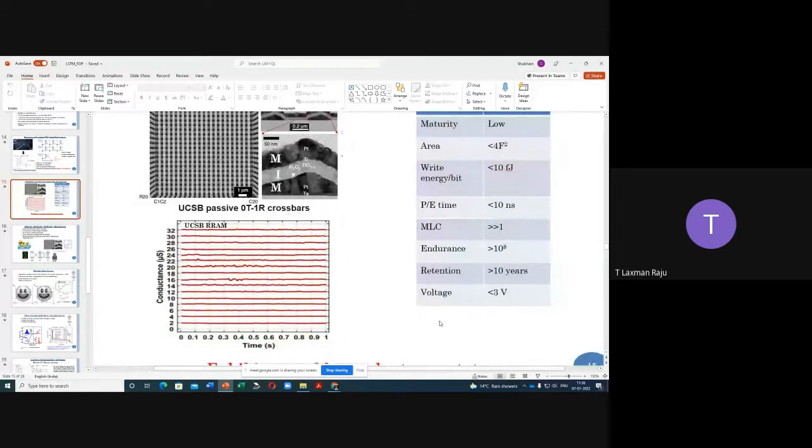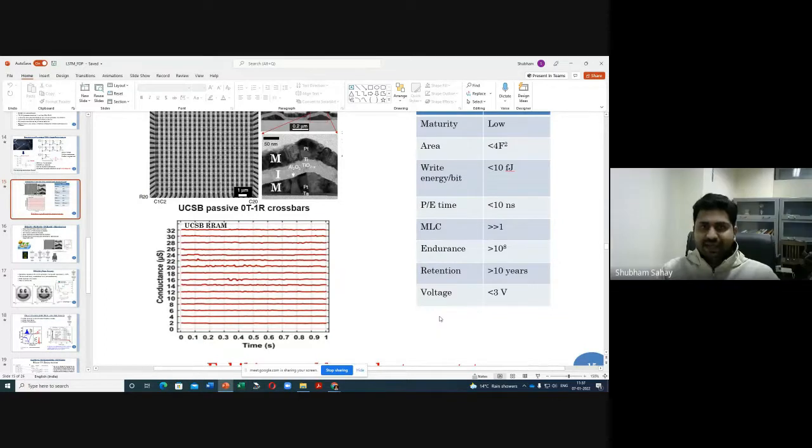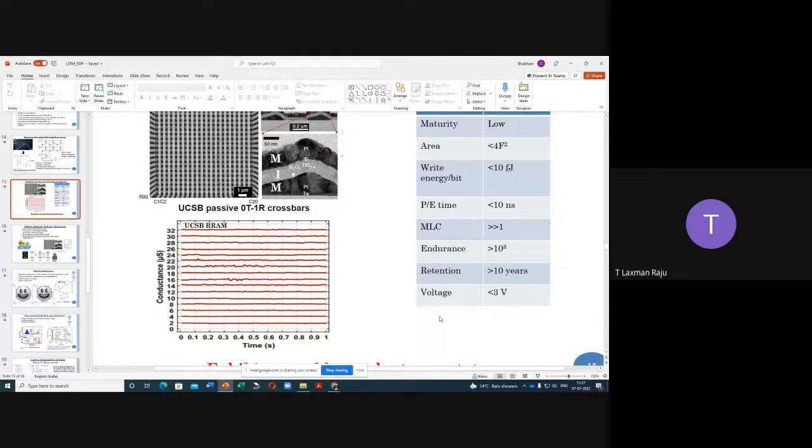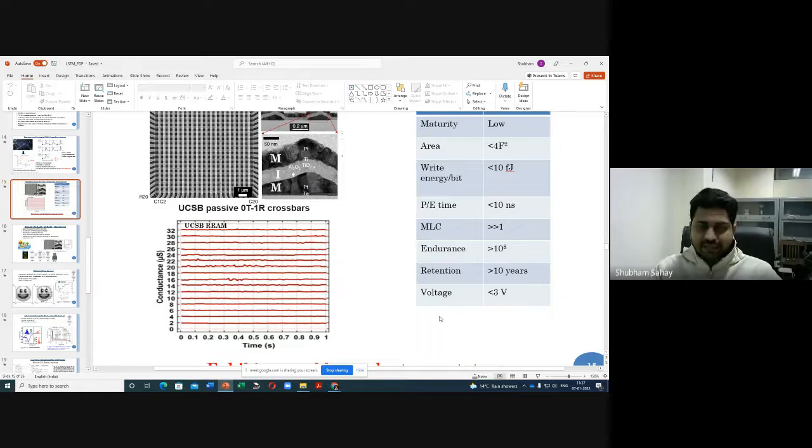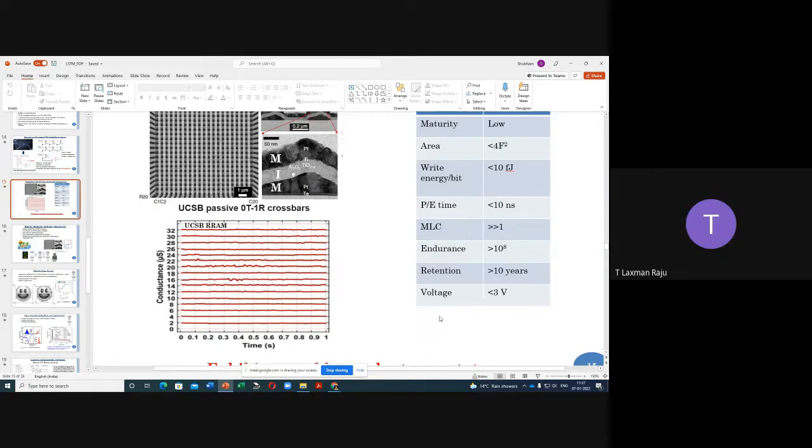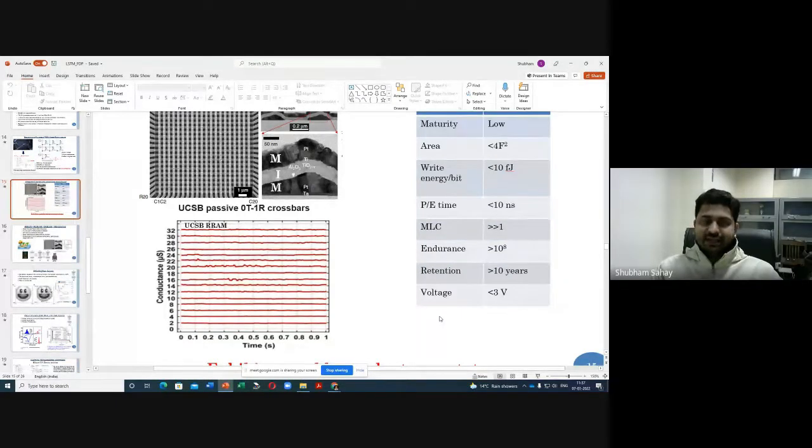Here, the MIM structure, I see you have platinum, and you are sandwiching TiO2 and Al2O3. Yeah, Al2O3 is the barrier here. Al2O3 is a barrier layer, which prevents... I know you worked on the simulation side, but I see TiO2 minus X. That means there are oxygen vacancies. Yes, each oxygen vacancy will leave 2 electrons. So in that structure, TiO2 is not working as an insulator but rather as a conductor. Exactly. Well, not a conductor, it's still not showing very high conductivity.